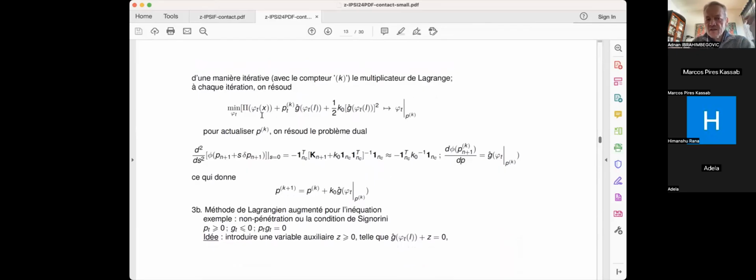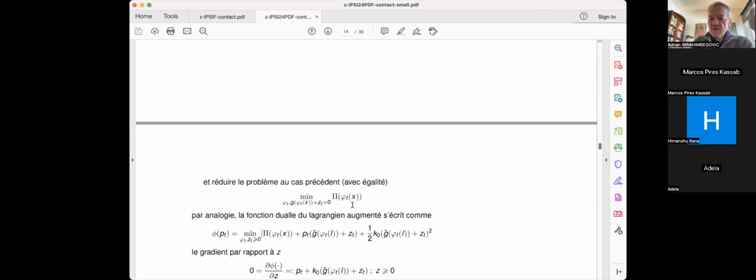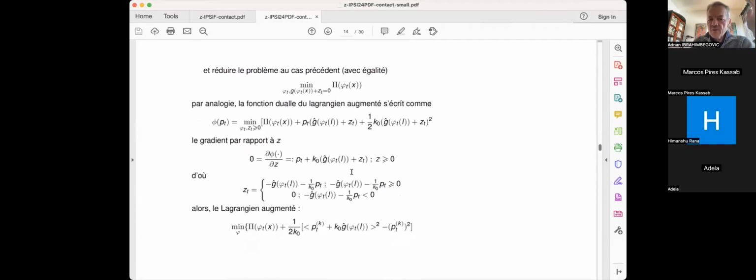So here, what is it? You are minimizing the strain energy function, the one with the penalization and the one which is dualized, and you're computing the proper value of phi given the iterative value of the pressure. The update of pressure should really be done with the real duality statement, that means with the full tangent stiffness and K0 times the rank 1 update for the last node. But what the hell, it's too complicated. Often people just replace it with K0 and do this linear update when they do the computation. And so in the process, you can recover the computation of your stuff.